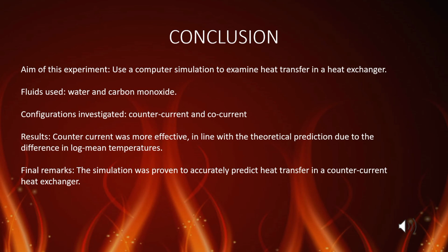The aim of this report was to simulate heat transfer in a heat exchanger using a computer simulator, namely ANSYS. For the simulation, two heat exchanger configurations were investigated, namely the countercurrent and co-current configurations. The fluids that were used were water and carbon dioxide. It was determined that the countercurrent configuration was more effective at heat transfer, a result which is in line with the principle of a greater log mean temperature, which is the driving force for heat transfer. Overall, the simulation was successful at demonstrating the heat transfer in a heat exchanger that is predicted.